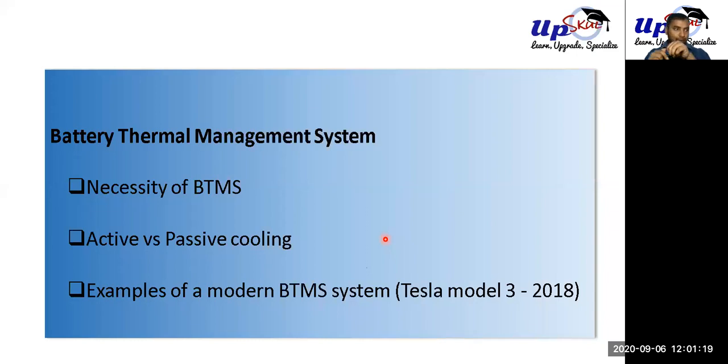Okay. So as the powertrain engineer or as the mechanical CAE engineer, this will be your job: the thermal management system. Why do we call it the thermal management system? Why don't we call it the cooling system, like the engine, right? That's because batteries need cooling, but batteries also need heating in cold environments. Batteries are like humans. You cannot keep them very cold or too hot. Anywhere you would feel uncomfortable, you should not keep your battery.